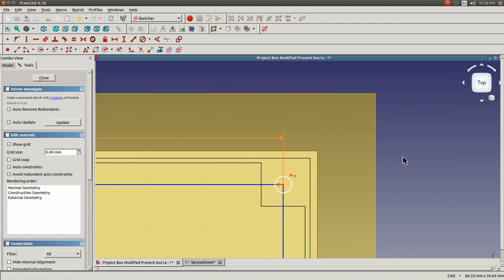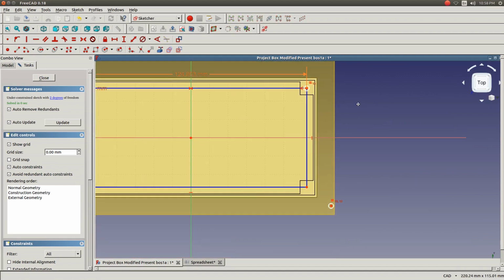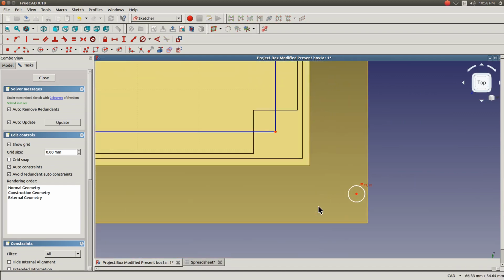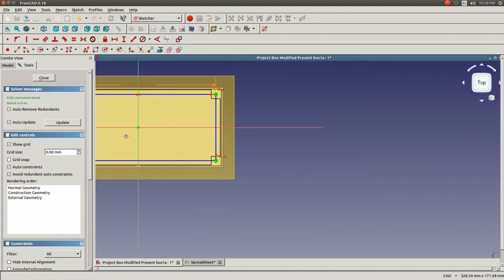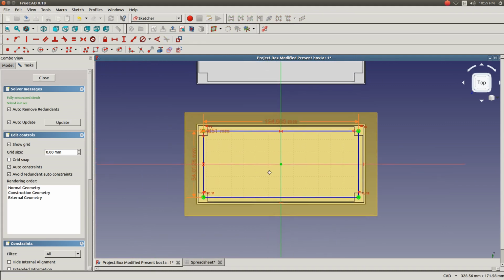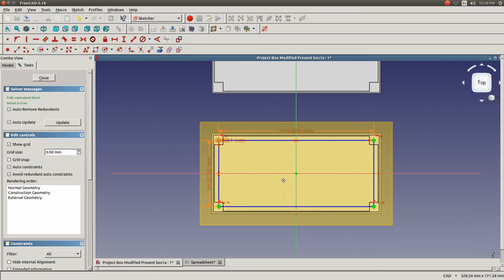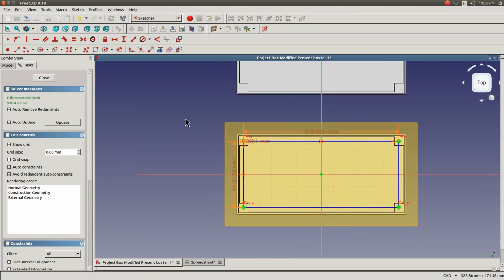Although I haven't mentioned this before, I make extensive use of the point constraint tool to fasten things together instead of just connecting them point to point. This is because the point constraint tool is a constraint just like the symmetry or dimension constraints. I learned the hard way that this approach keeps your sketch from falling apart when you change dimensions in your spreadsheet.